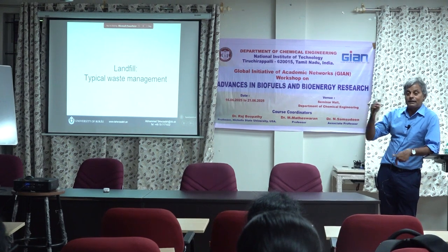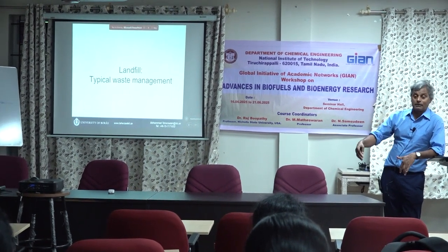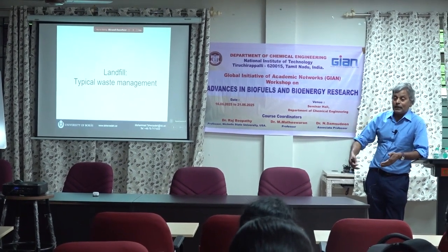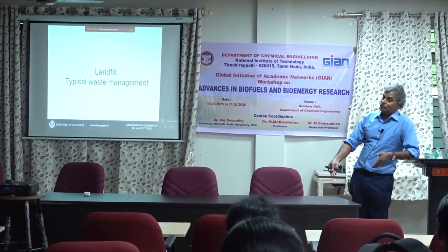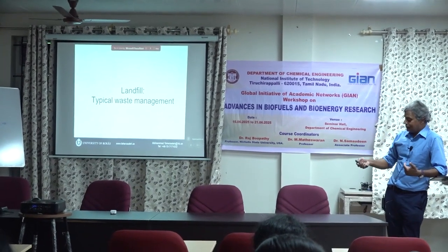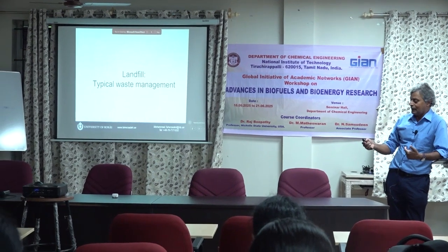And everything we talked about in the morning about anaerobic digestion is what's happening in the landfill. So when you compact it, you create anaerobic conditions, and then after 5 years, you recover methane gas from a landfill. Okay, so it's a very common practice in the Western world in sanitary landfills.